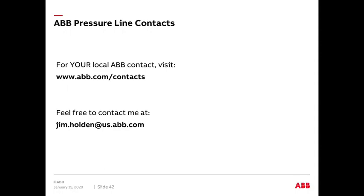Yeah. Right. So typically a pressure transmitter is what we call characterized. So you're going through an environmental chamber and you're applying different pressures at different temperatures. And basically what you're doing is you're teaching the electronics how that actual sensor, let's say it's a piezo crystal, reacts at the different pressures and temperatures to stimulate how much electricity is coming out of that. So once you go through the chamber and you do the characterization, the temperature shouldn't really have a lot of effect either. And that's something you'll look at. You'll see people grade their pressure transmitters over different temperature ranges too. So that's how temperature is affecting that.